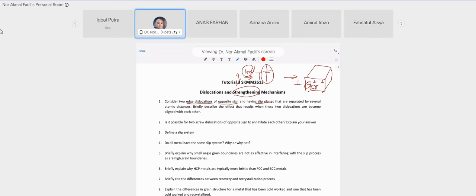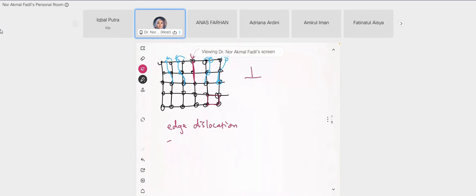So at this point, just to tell you that if we want to have zero dislocation, we allow the slip to move. Okay, the reason why slip can move is when we generate heat, they can arrange themselves and they will cancel each other. So there will be zero edge dislocation, zero defects in the material. So the way that we allow this, basically we induce heat and the atoms will move because there are stresses. There are stresses inside the metal. There are stresses because of this extra plane. So they will arrange themselves.